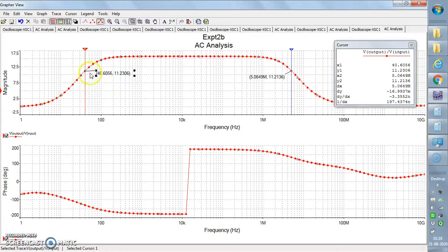Okay, 11.22. See, whatever is the maximum voltage gain we have obtained when the vertical axis is linear. So the bandwidth, how to obtain this? Now this becomes F2, this becomes F1, or this becomes upper frequency minus lower frequency. So these lower cutoff frequencies are decided by 2 coupling capacitors and 1 bypass capacitor. And the upper cutoff frequency is decided majorly by the internal capacitances of the MOSFET, which has multiple internal capacitances that also play an important role in deciding the corner frequencies. So in this way, the difference between these two gives the bandwidth of this amplifier.